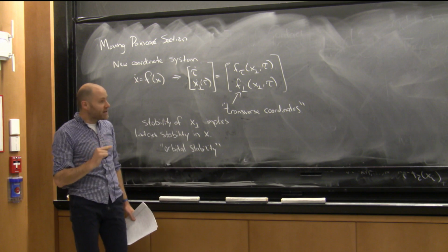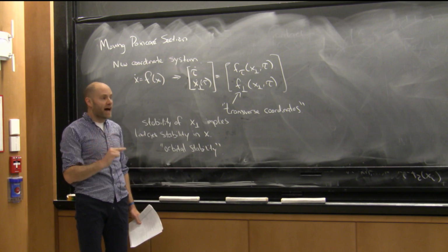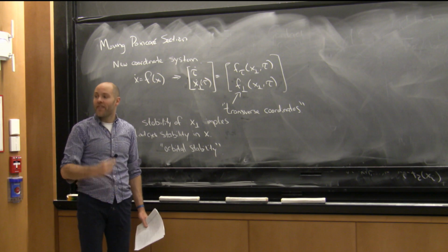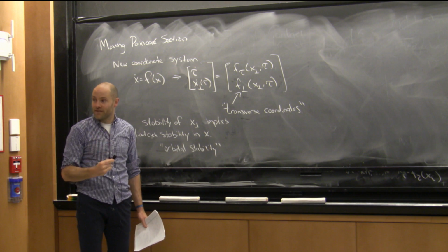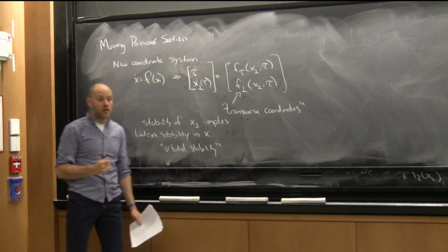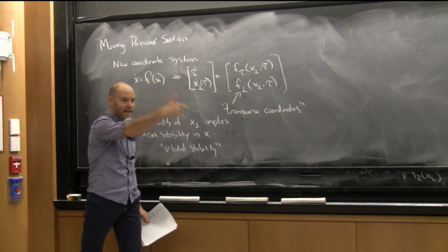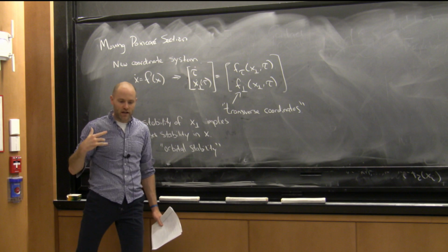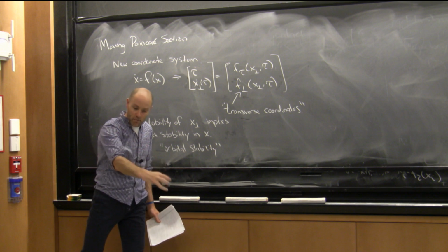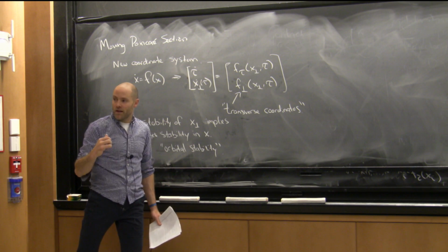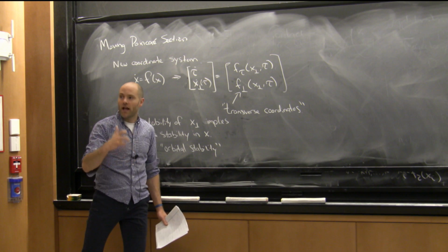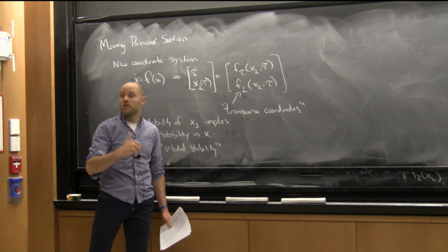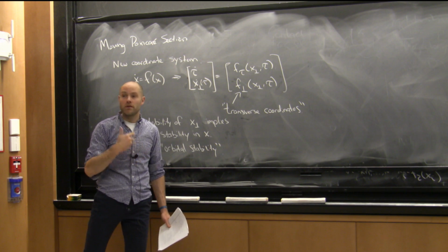So this is not specifically tied to orbits until I use the word stability. And then I feel that it is fundamentally tied to orbits. If I talk about a finite time, did I get to the perch or not? It works for trajectories. If I care about whether I successfully picked up the mug, that works for trajectories too. But I won't use the language of stability, and even the language of Lyapunov requires more details and more care. It's possible to use, but it's simpler to describe in the infinite horizon.